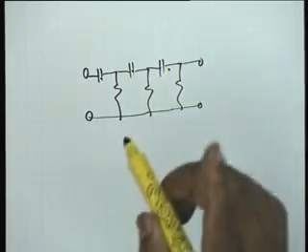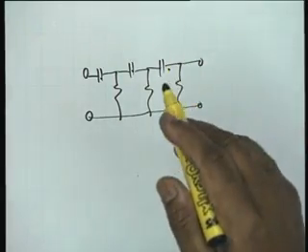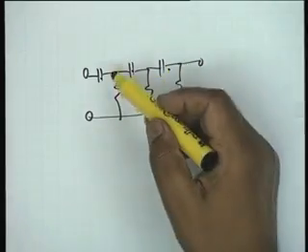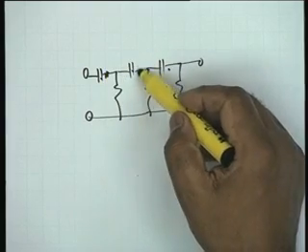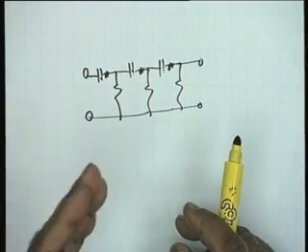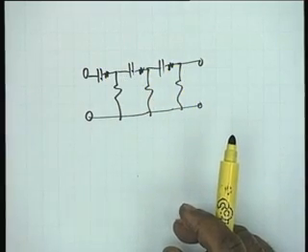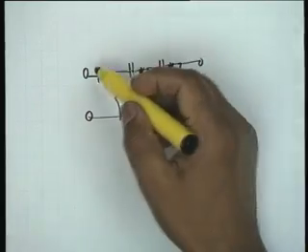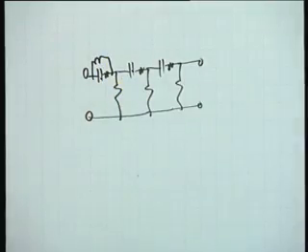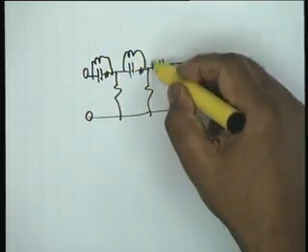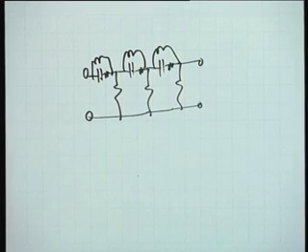So it can have multiple zeros of transmission at any point in the S plane. Suppose we had a resistance here, then obviously this zero would have shifted to the negative real axis. Suppose we had an L here, then identical. Then these zeros of transmission would have been complex. Alright. Therefore, it is possible for a ladder to have multiple zeros of transmission anywhere in the S plane.